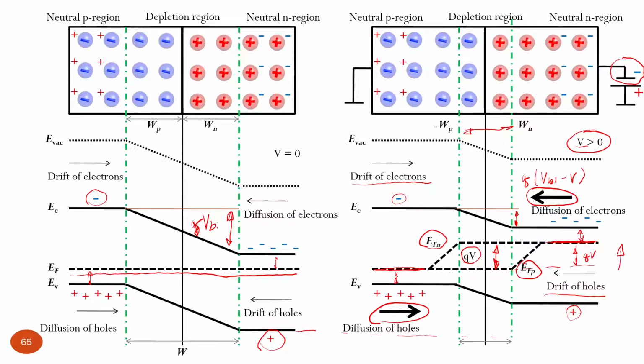So that always makes sense when you want to see the degree, like quantify some parameter which pushes a semiconductor or p-n junction out of equilibrium condition. You always want to look at the splitting between Quasi-Fermi levels, because the more they are split, the larger this disturbance. In this case, the disturbance is external bias, and that's why we can quantify this splitting of Quasi-Fermi levels by